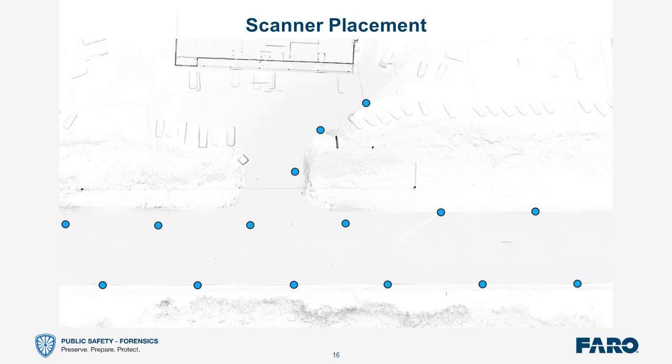The way around that is to scan in laser without color, using just the infrared laser, and therefore it does not show up at all. I forgot about the grayscale option there. I'm almost always colorizing my scans before I go in, but again, it depends on the situation, right? Good thoughts, thanks.